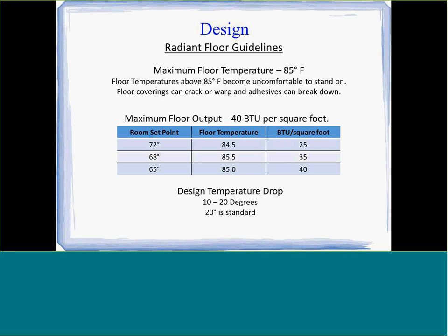I typically design at 20 degrees. It makes things a lot more efficient from my point of view. You get the most heat transfer at 20 degrees, and so that's where I like to design. I do see jobs come out at 10 and 15 degrees, which is fine. You just need to move the water a little quicker, size your pumps a little different, and you're not going to get as much heat transfer through the tube when you go to the lower temperature drops.